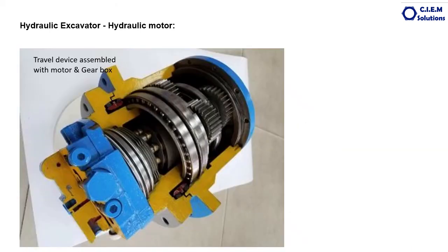And when we see the brakes, what we discussed, when you cut any travel device or swing device, for example, this is the travel device, looks like this. The complete bottom portion is the reduction gear unit with the planetary gear set. This complete portion is the motor unit. These are the pistons, this is the tapered swash plate. Inside there will be the cylinder barrel housing. You see these plates, what I told you, these are the disc plates, brake discs or clutch discs. They are always held together with the help of a spring, as I told you. So whenever we want to release the brake, oil is supplied from one of the ports here, acting pressure on the internal springs, making these clutch plates free from each other, allowing the motor to rotate freely.